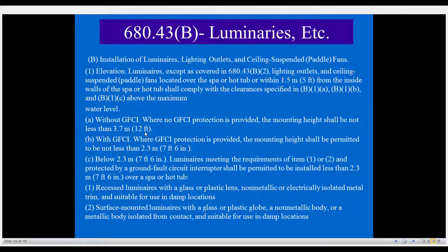Okay, and if it's got GFCI protection on that circuit, then it shall be mounted at a height that's not less than 7'6". So I can come down a little bit if I add that GFCI protection. One thing I do want to remind you is that ceiling fans have a listing, and they have installation information, and it's going to give you a minimum height that you need to mount these fans to.